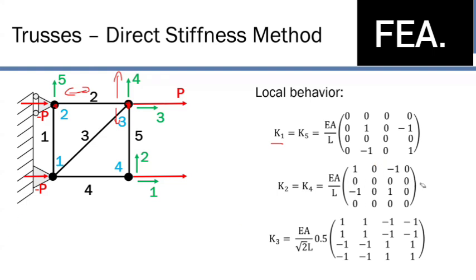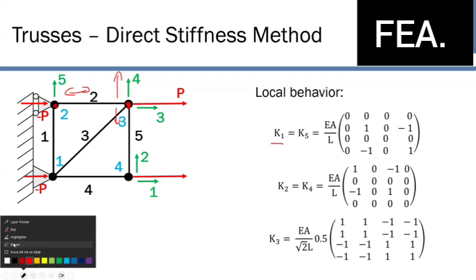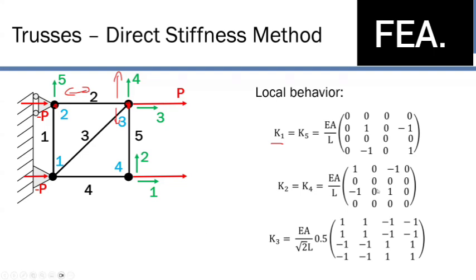So then zero, anything in the two direction, like we've mentioned in the perpendicular direction, that's not really going to affect us or generate a force because it is a horizontal member. And then looking at that third row, the -1 comes from, obviously, if we move this one now, the other one is going to exert an equal and opposite reaction. So we get a -1 right there. And then for the second joint right here, that second node, if we move it to the right, it's going to generate a positive force to the right, and so on. Does that make sense, everybody?